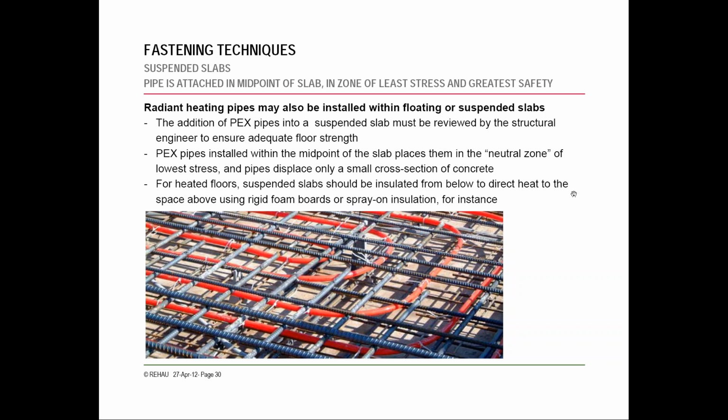You do want to install the pipe at the midpoint in the slab if you can, depending on if you're going to be insulating the bottom or if you're going to allow it to penetrate the top and bottom, which you may do with a heating and cooling application. It might depend where you can put it in the slab. Also, the structural engineer might tell you, hey, I can only put it at a certain area. When you get to these more complex situations, you want to touch base with the manufacturer and see if they have a specific recommendation. But normally, it'd be your standard installation techniques.